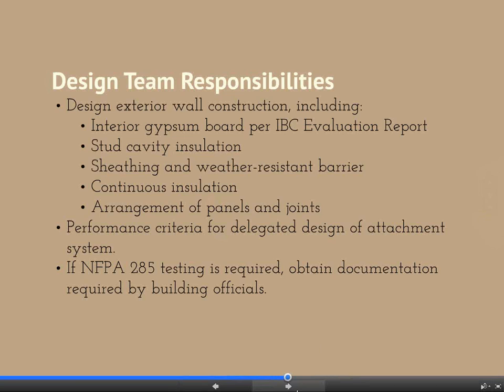And those are a wonderful product. They are fiberglass units that you screw to the studs, and they are structural, and then the metal furring goes on top of that, and then you connect to those. The problem is that they can only be used with non-combustible mineral fiber continuous insulation, but they are very effective because they are not thermal bridges.